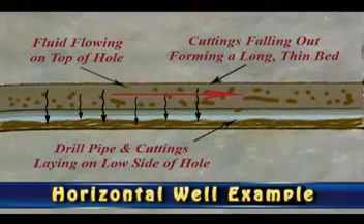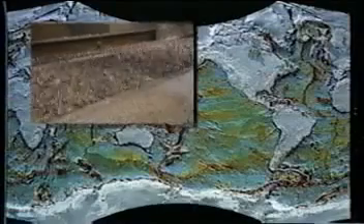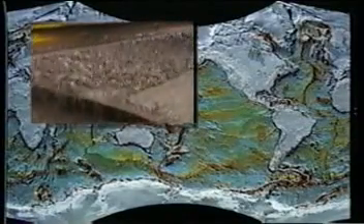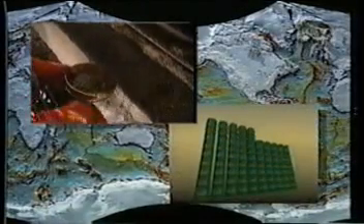As the well inclination reaches about 65 degrees, the cuttings will stop sliding downhole. Now, instead of a large cuttings bed forming in the well, a long, more evenly distributed cuttings bed will develop. Very large volumes of cuttings can exist in these hole sections. For example, a 2-inch cuttings bed in a 10,000-foot section of 12¼ inch hole is approximately 85 barrels of cuttings in the well.